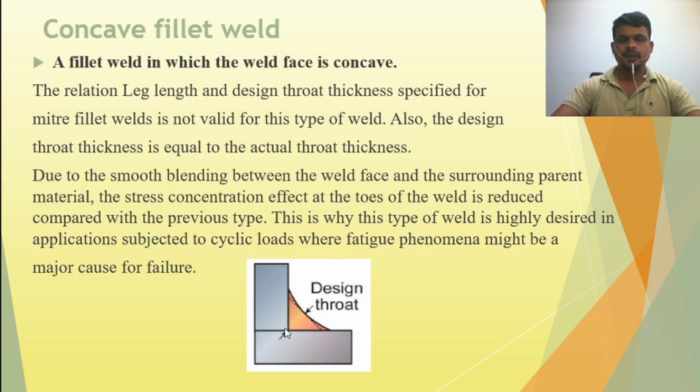So this type of fillet weld is very important where cyclic load is working, so there can be fatigue cracks. For this type of condition, we need to design a concave fillet weld. If you want to calculate this also, you see the actual throat thickness is only the design throat thickness. So I hope you understand this topic.